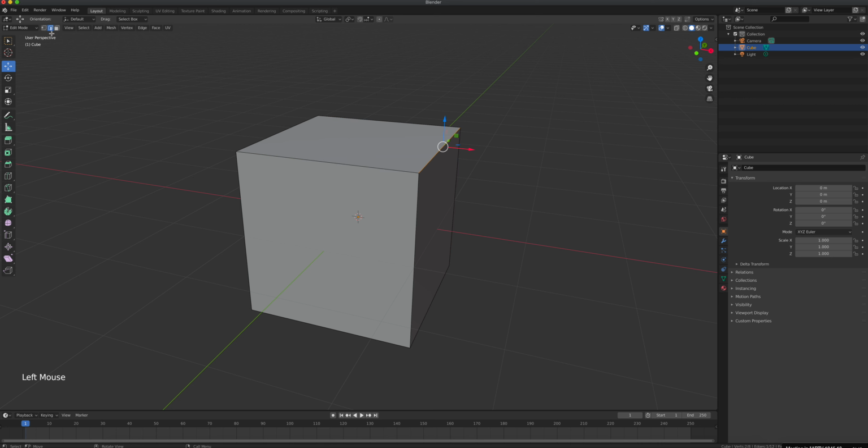The second one is line or edge. Okay, when you select that, you get to select the line. So basically 2 points, minimum 2 points, you get a line. Okay, you combine multiple lines, you can create a polygon face, which is number 3. So this is number 2. Okay, and then if I press number 3, it switches to the third one, or polygon face select.